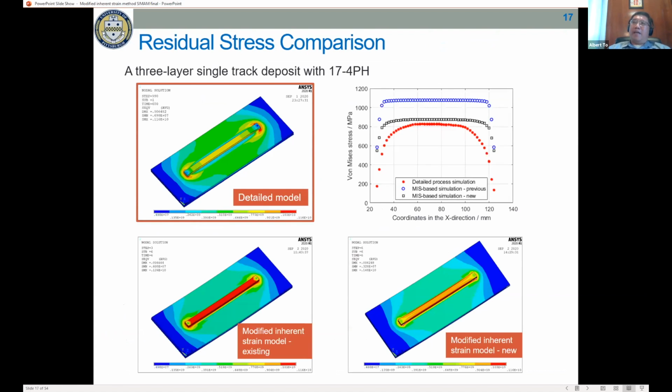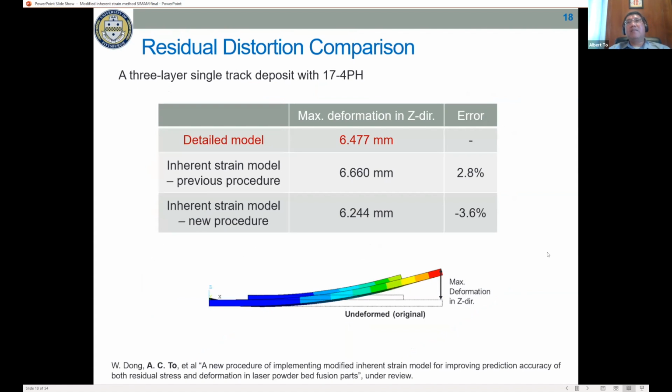The stress becomes a lot better in this case. Previously there was a 20% difference in the deformation stress if we only applied properties at 1 temperature, and now with properties at 2 different temperatures, the result becomes a lot better for the stress distribution.